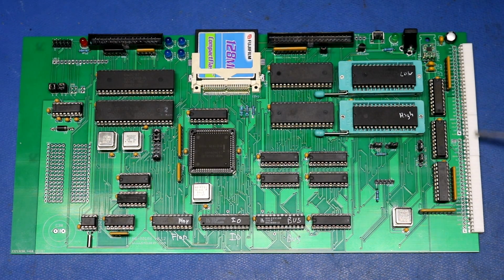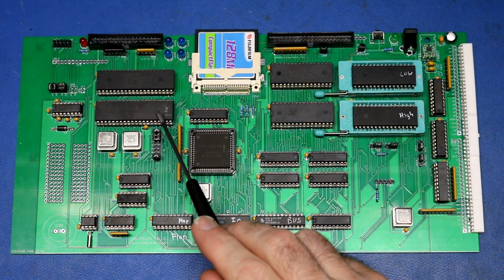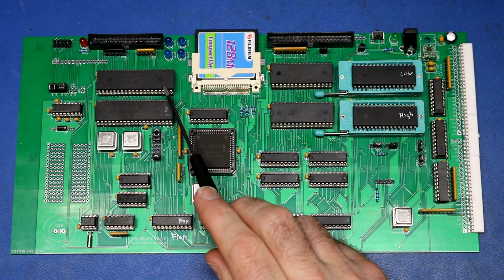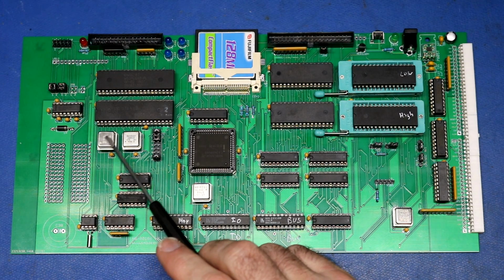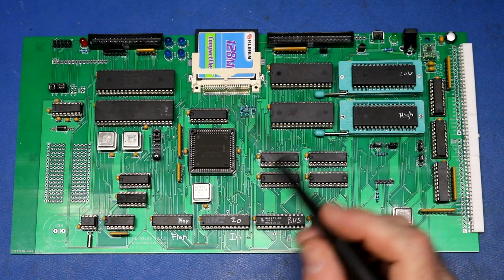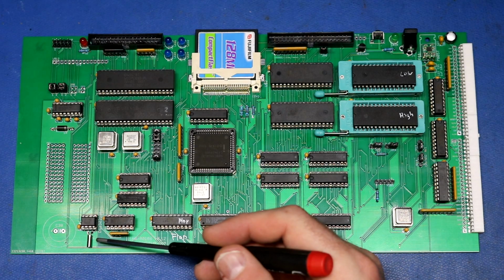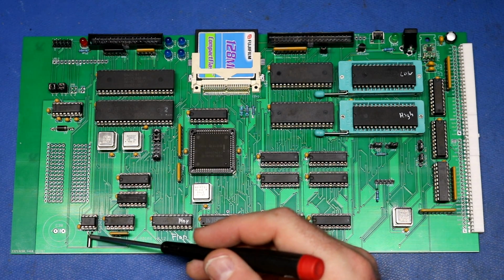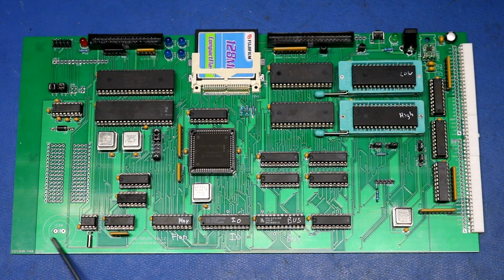Over here we have the H8 bus connector and the bus transceivers for the H8. Over here for peripheral devices we have our 16550 UART and our WD37C65 floppy controller and their associated crystal oscillators, a 1.8432 megahertz and a 16. Down here we have our real-time clock, Dallas 1302, with its associated 32.768 kilohertz crystal. There's a spot for memory backup using a super cap, not currently populated.